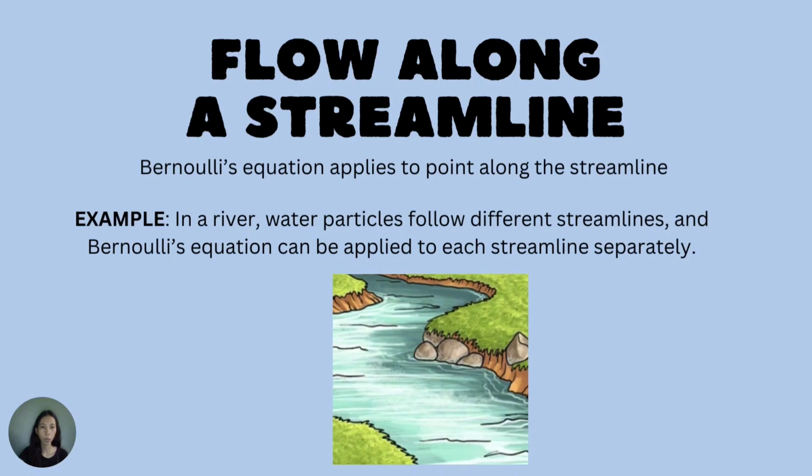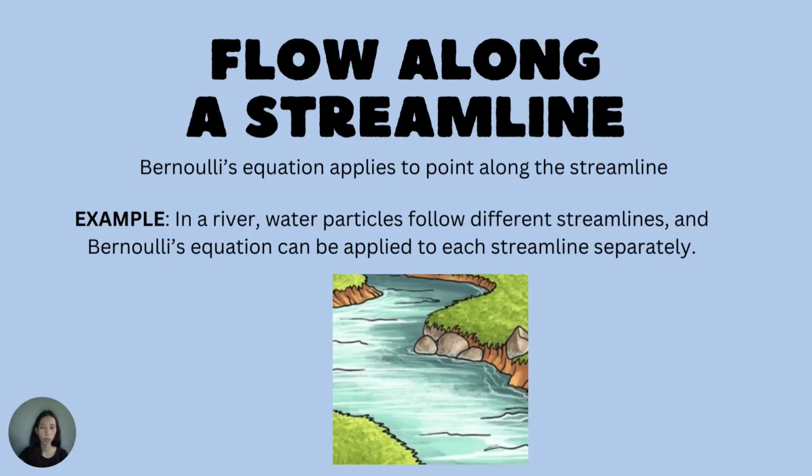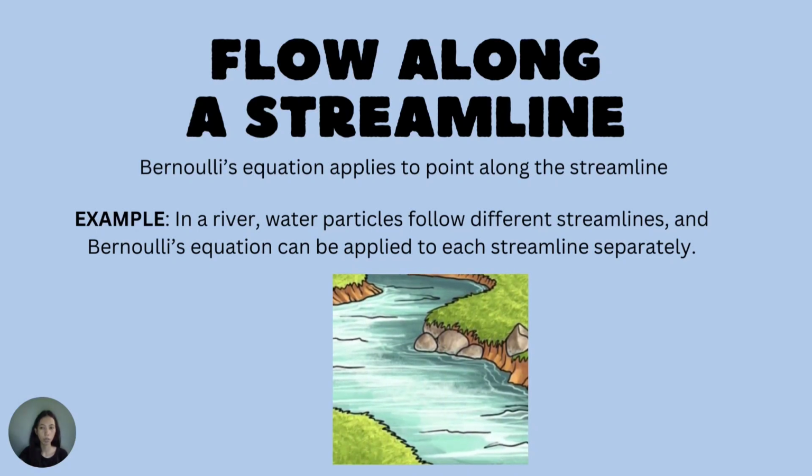When we talk about flow along a streamline, we mean the flow of a fluid along a path where the velocity vector at every point is tangent to the streamline. Bernoulli's equation, which describes the conservation of energy in a fluid flow, applies strictly to points that lie along the same streamline. This equation states that the total mechanical energy per unit mass of the fluid remains constant along a streamline, assuming the fluid is non-viscous, incompressible, and there are no external forces acting on it except for gravity.